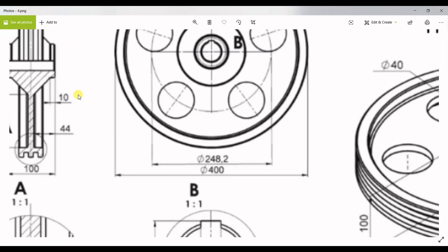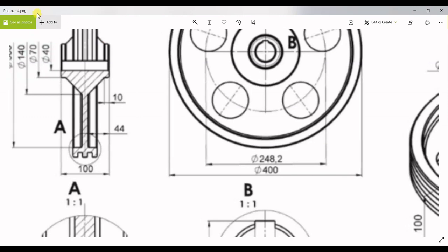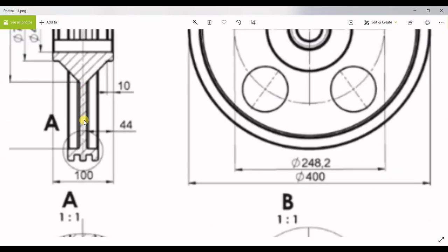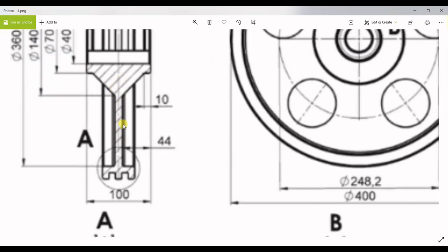Generally, in some components as we have designed earlier, we have worked with a component which was having an I section. But this component is not an I section, it is something different. And that is represented with the shaded region. So following the dimensions given to us, let us initiate the 2D sketching first, and then let us convert that 2D sketch into a revolve geometry.